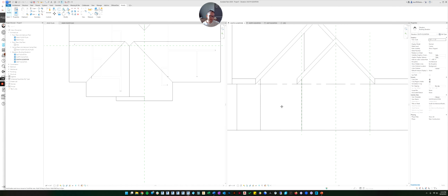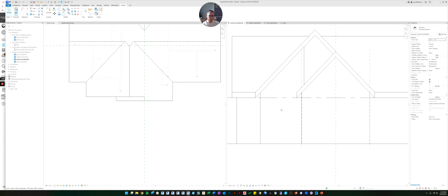Sometimes you just like to click in the middle of it and have it select it. So in that case, if you'd like to select the wall by clicking the middle, if you go down here, there are these little selection tool options. If you hover over this, the fourth one in, it says select element by face. Right now it's got a little red X, which means you can't pick the face of something.